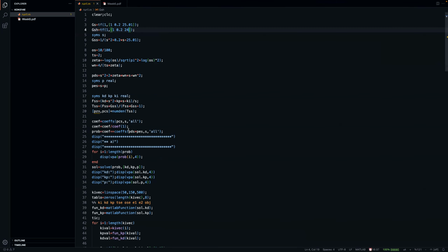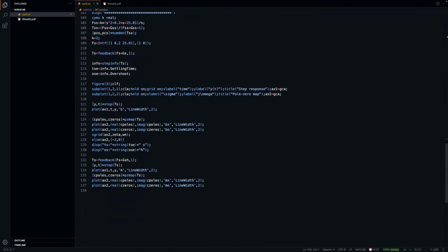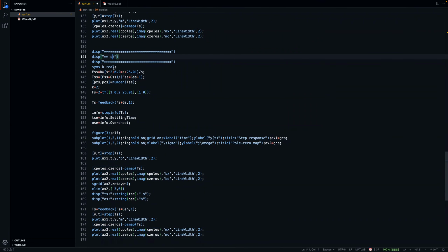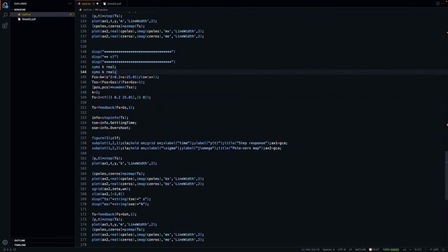So now, when we look at our response that we did come up with here, let me just copy the whole thing here. That's going to be C. Now we can see that just one pole here doesn't cut it, because the closed loop is going to be a first order one. So what we can do is either you could just see directly what you should place, which in this case I can, and I'm going to do it. Or you might want to go the safe route where you say, okay, I don't know where I want to add this pole, but I know that I'm going to add another pole to our controller.